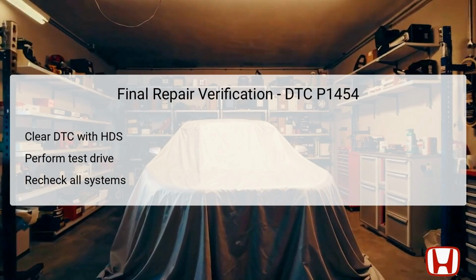After completing all necessary repairs related to DTC P1454, it is crucial to verify the effectiveness of the intervention. Start by clearing the fault codes again using the HDS, resetting the engine's diagnostic data. Taking the vehicle on a test drive allows for real-world conditions to be evaluated. During this drive, monitor the vehicle's performance, ensuring there are no lingering symptoms related to the FTP sensor or the evaporative emission system.